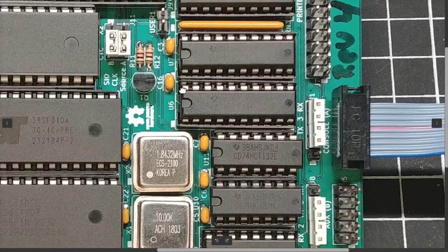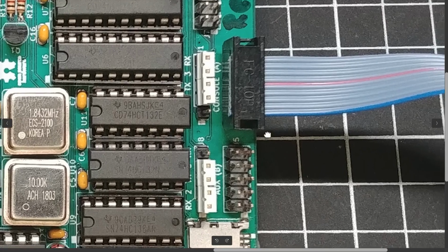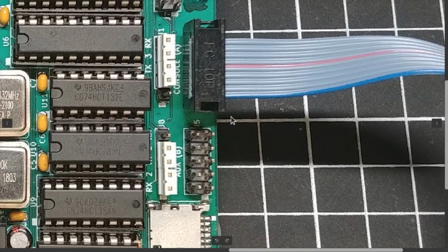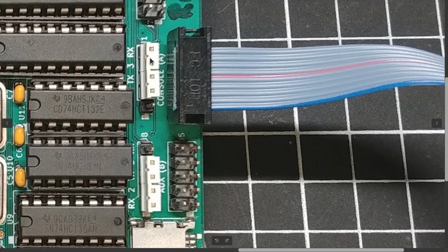All right. Now, somebody posted me a note the other day, an early builder of this thing, couldn't figure out why they weren't getting any data, and then they figured out eventually that they needed to put jumpers over here as well. Well, let's talk about these jumpers for a minute. This is a feature. If you do not put these jumpers in, the cable here, which goes to a DB9, will not be connected to your board. They'll be floating. These are a requirement, okay?